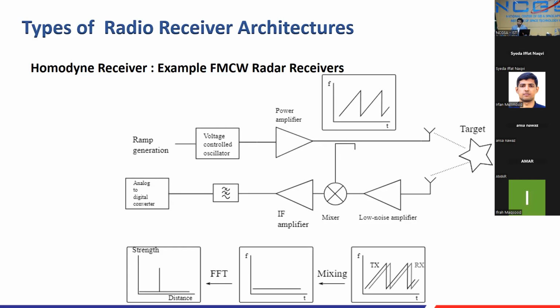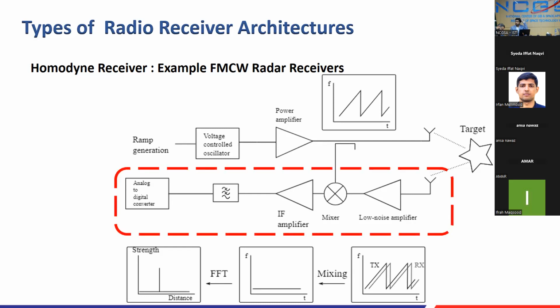So in practical application in radar systems, if you miss a small chunk near DC, you are missing the target information in that range. That is actually termed the blind range of an FMCW radar system. That was the receiver.